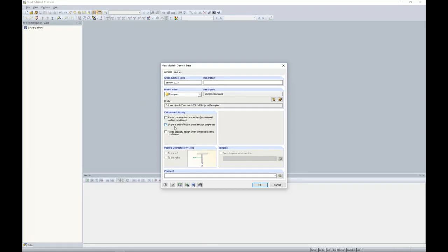Now this is the width to thickness ratios of our different elements that comprise this cross-section. So this includes flanges, webs, any of the lips or extruded sections. Now why this is so incredibly powerful is that when we take this information of these width to thickness ratios into RFEM and eventually into the aluminum design module, we can actually check all of them for local buckling.